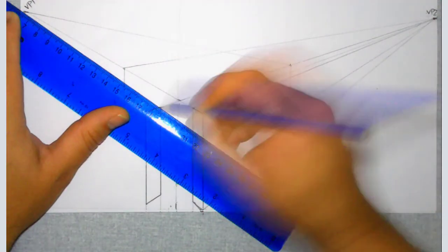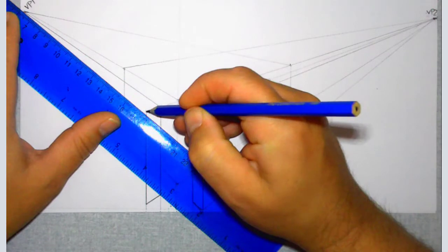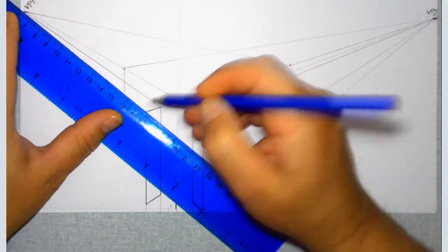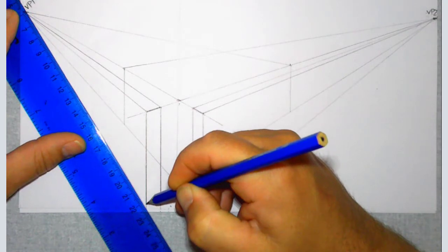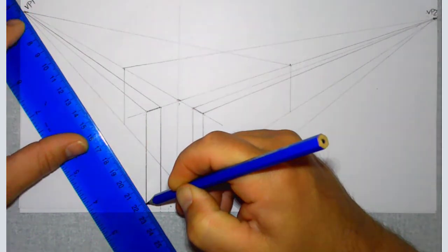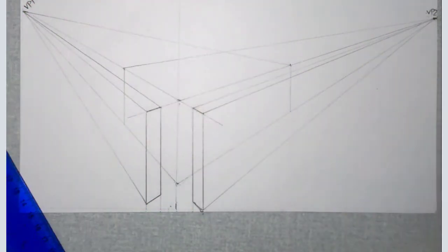So you know, if your pencil's getting a bit blunt, stop and sharpen it. If you're drawing too heavily, take a bit of pressure off. Keep checking that you go into the vanishing point, and the same point on the vanishing point. I'm noticing that my lines were creeping out there where I was going a bit quick or talking.